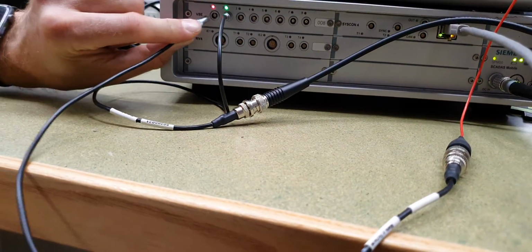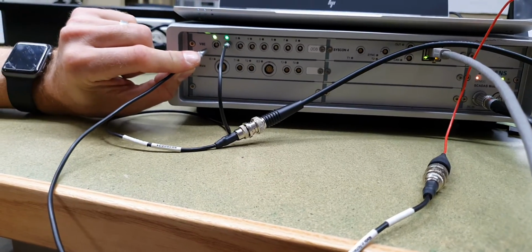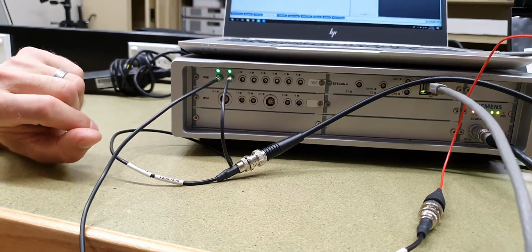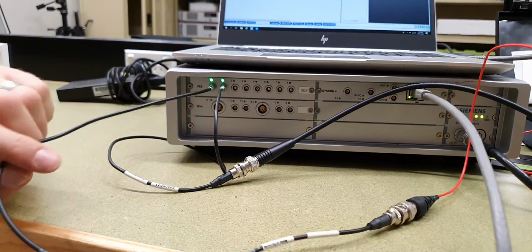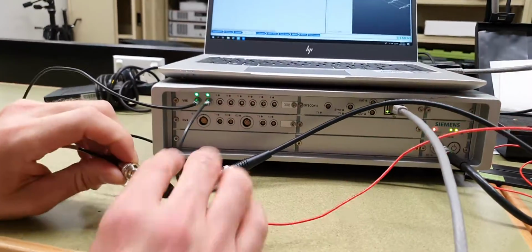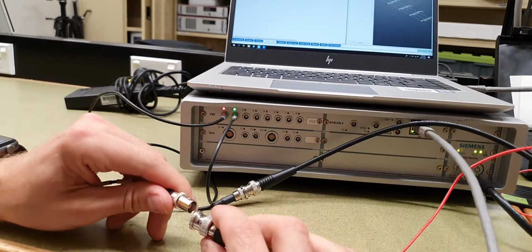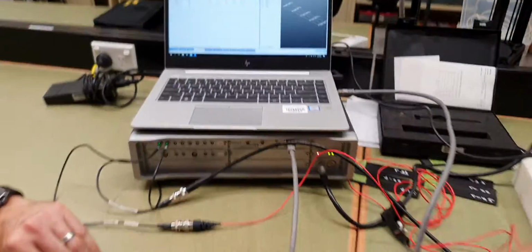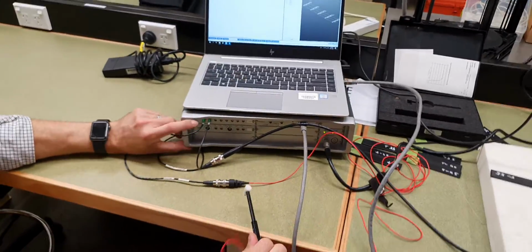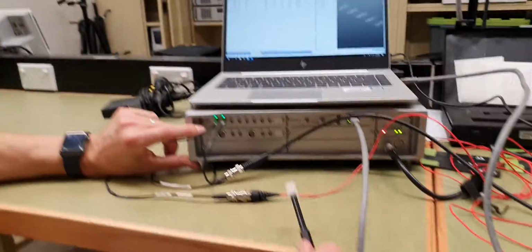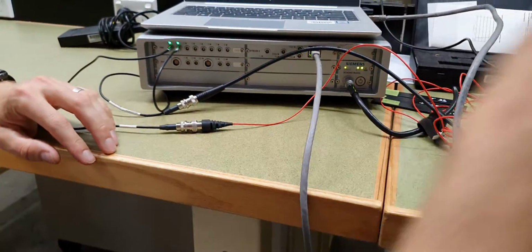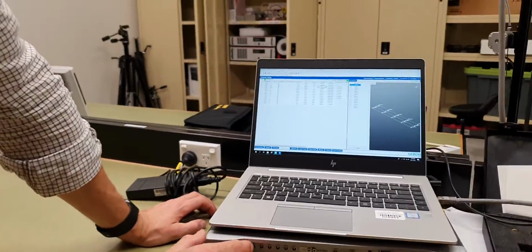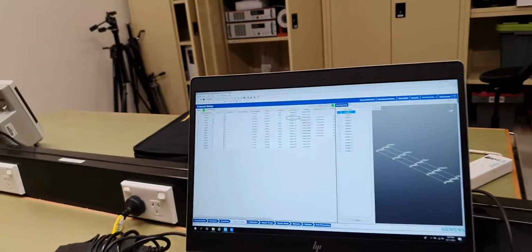It's flashing, telling me basically that there's nothing connected because it knows it's not conditioning a channel. When I connect this, eventually it will power the transducer, and then it goes to solid green. If I break the cable, if there's a problem, it goes back to red. So it gives me some indication that the measurement chain is good. It will also flash red on the acquisition system if I get overload, if I've got too much measurement from the transducer, and a range of other reasons. So it's useful to always keep an eye on the front end on a channel by channel basis.